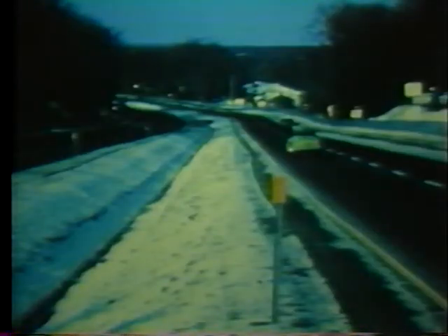Here, you see a ditch with 2-to-1 slopes that is extremely hazardous. It is far too close to the roadway for the steepness of its slopes. Installation of an underground storm sewer system appears to be the only way to improve the cross-section.